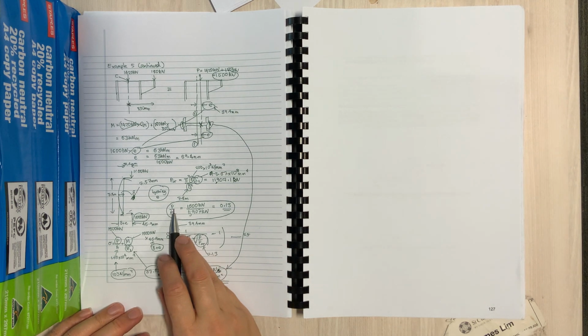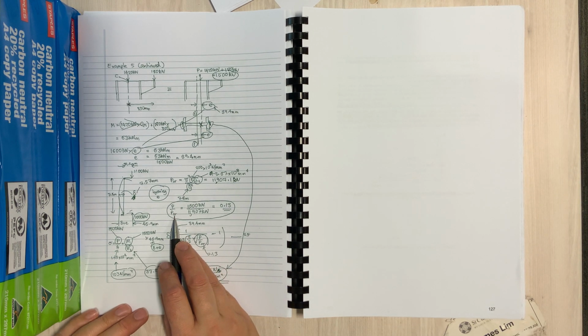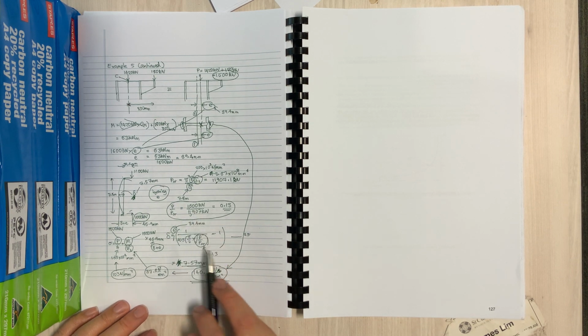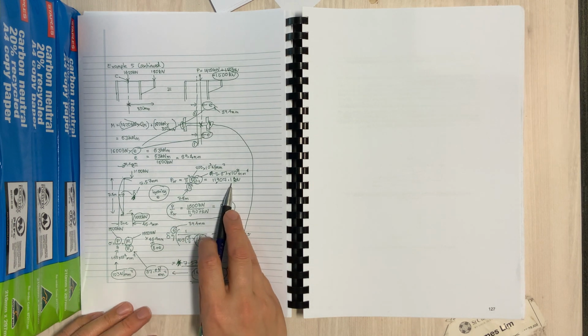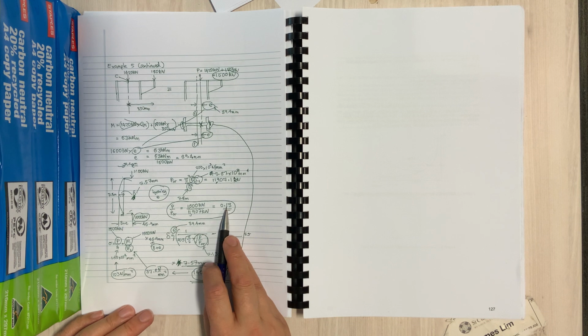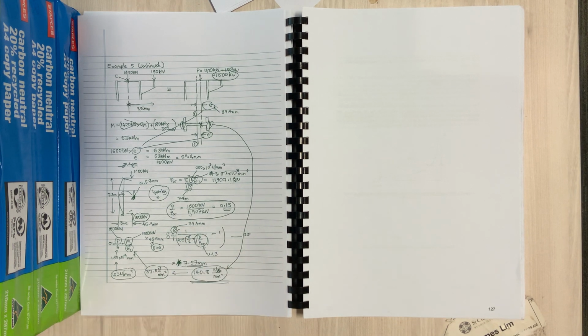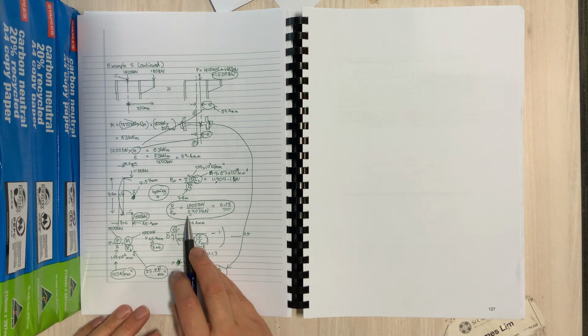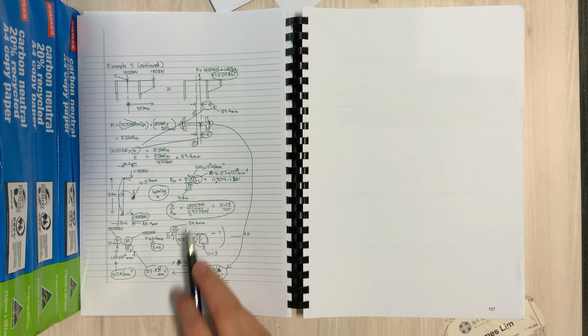So you can work out your P over PCR. We know the P that we've applied, which is 1600, the total P, and we know what PCR is because we've just calculated it. So the ratio of P over PCR is 13% or 0.13. This means that the load P is nowhere near the buckling load of 11907. Nevertheless, for any column under any axial force, the effect of buckling needs to be taken into account in the calculation.